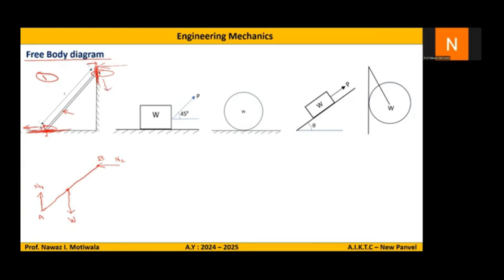So this is the direction of motions for point A and B. Friction force will be opposite to these directions. So if I make the friction force at point A, the motion is towards left, so the friction force will be towards right side. So I make one force which is on the right side, and I will name it as mu multiplied by N. That is friction force at this particular point.